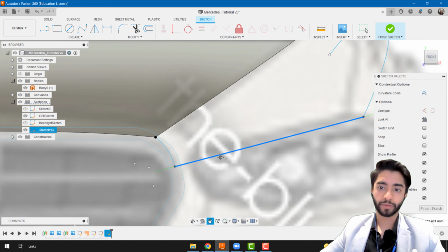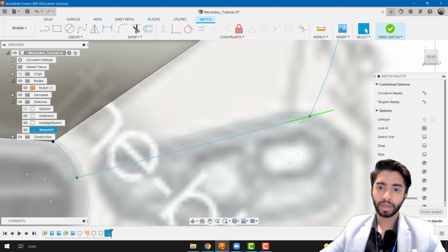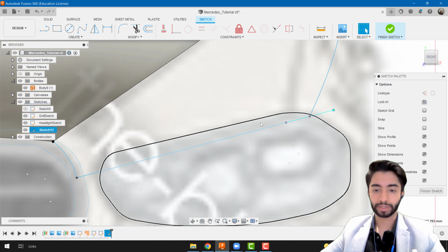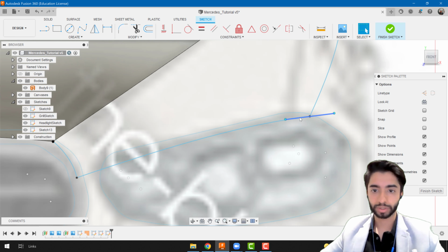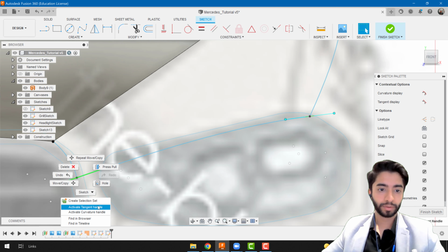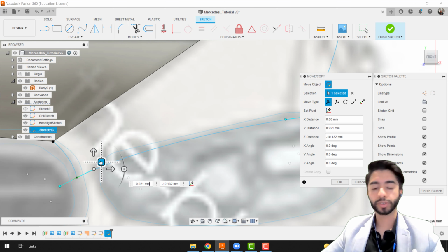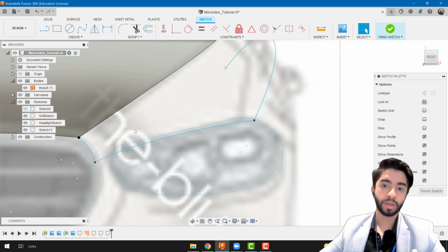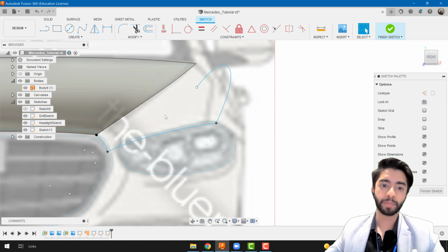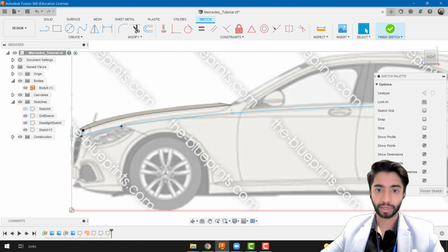So we're going to repeat the process for this as well. So if we switch on our headlight sketch, we want to make sure that this line here, again, just activate tangent, is following a little bit, at least matching or trying to match that curve over there, right? Again, if this is not making much sense, try it out yourself and you'll see the problems you run into, and then start rewatching the video in bits to try and see why what I'm doing makes more sense. Okay, so we've got one more section to complete, and that's that back section over there.